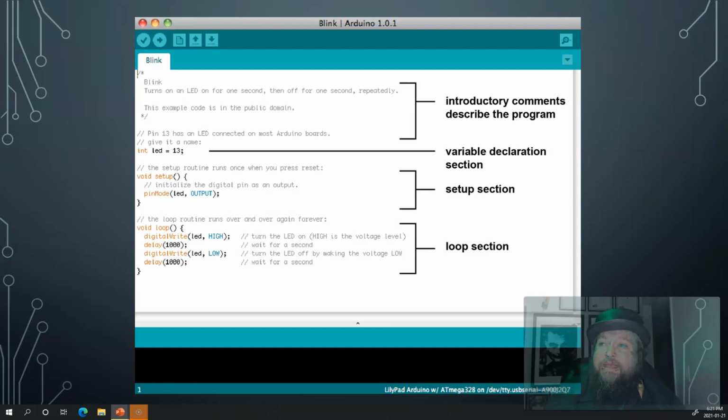But when you're looking at any example programs in the very beginning, and you can see different syntax and everything here, generally you still have comments and things like your introduction for the program. You get your variable declaration, which is called global, and there's a difference between declaring a variable here versus inside. You've got functions and everything else. But then you have special things like what's called your setup function and your loop function, and the stuff that happens within them. They're very important because every program will have global variables that are always accessible. You'll have local variables as well. You will always have a setup function, and you'll always have a void loop function right here.